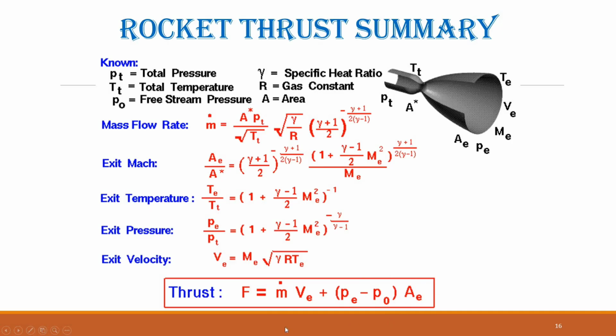In words, thrust is produced first by the momentum of the exhaust leaving the engine and second by the pressure difference acting over the nozzle exit area. When a rocket operates in a vacuum, the ambient pressure P sub 0 is nearly zero, so the pressure thrust term becomes very large and positive. At sea level, ambient pressure reduces this contribution. This explains why the same rocket engine produces more thrust in space than it does on the launch pad.